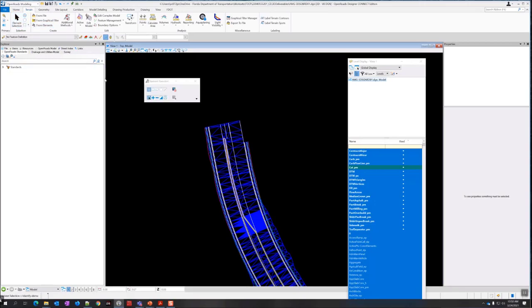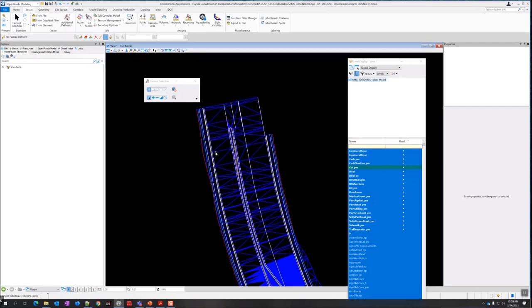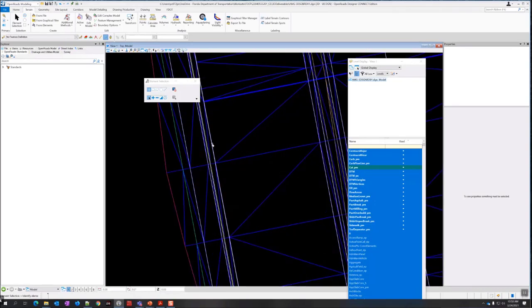Now we need to do the break lines for the subgrade. This is where it's saying it's important to not have any vertical faces. Also, it's important to not have any caves or anything doubled back. So when you're trying to avoid the vertical faces, you need to make sure that it's sloping out and doesn't create anything concave or double back in, because then it doesn't know how to put triangles on there.